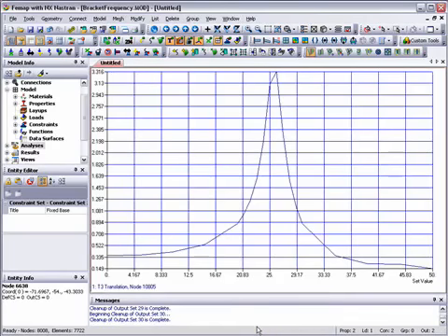All the data required to set up this XY plot is entered in the View Select dialog. The XY plot shows the Z translation of the motor center of gravity point. You can see that close to the first natural frequency at 26 Hz, there's a displacement of 3.312 mm, showing a dynamic magnification factor of almost 10 over the static response. The static response is visible at the left at 0 Hz. A more refined frequency sweep would probably reveal an even higher displacement value.